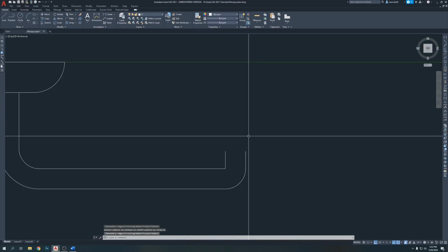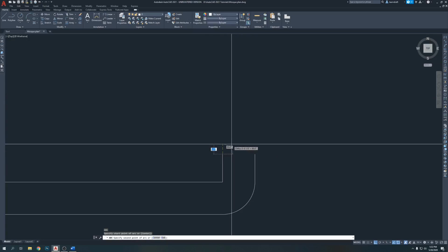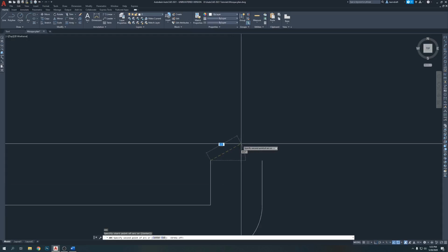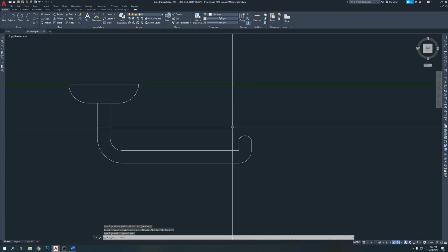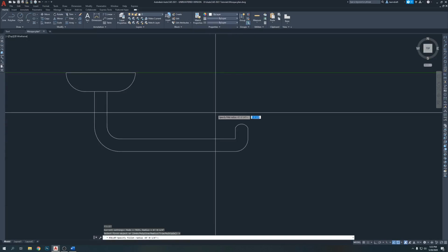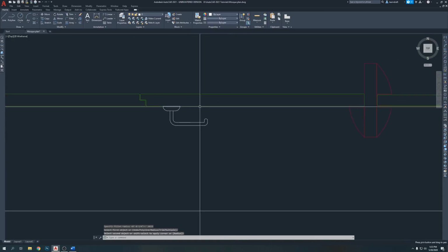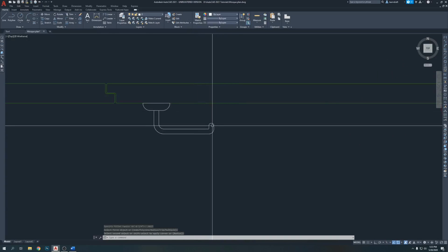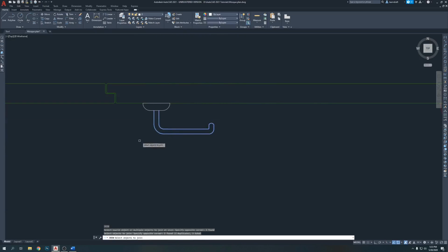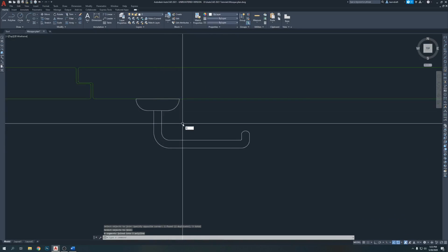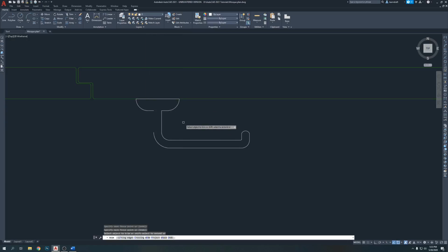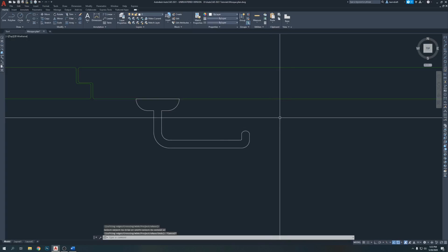Wow. Make a small, what is called, arc. So fillet, radius 0.0625, enter, which is 1/8 of 1/16. Okay. Yeah, join them together, so this frame is good. Actually, if I take this one out, how is it going to look? Looks good. No, join them together.